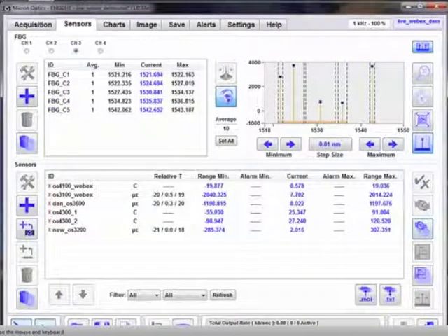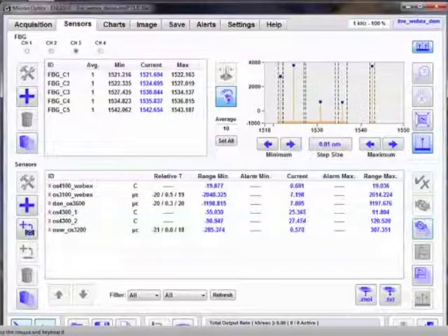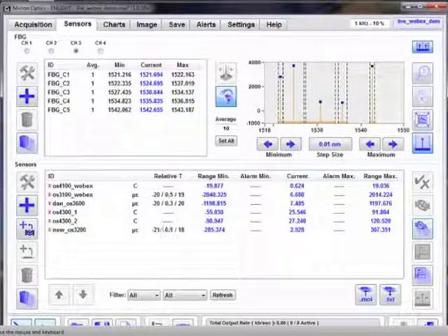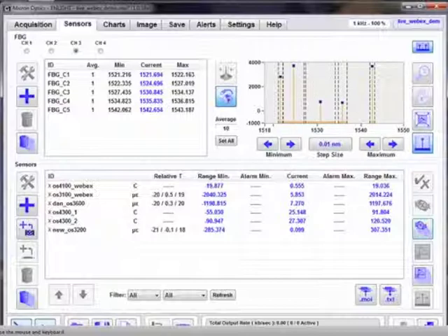Okay, so without independent sensor zeroing, if we were actually zeroing one common FBG value for that OS4100, we would have seen a step function in the value of the OS3100. Because it's truly independent, and each sensor element retains its own reference value for each FBG and its expression. Those are truly independent.